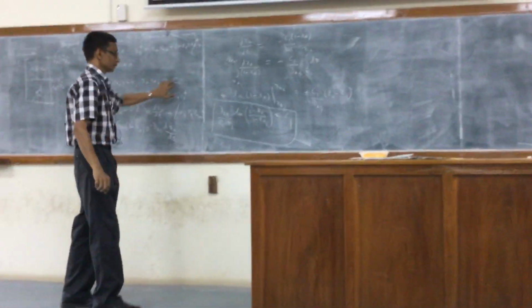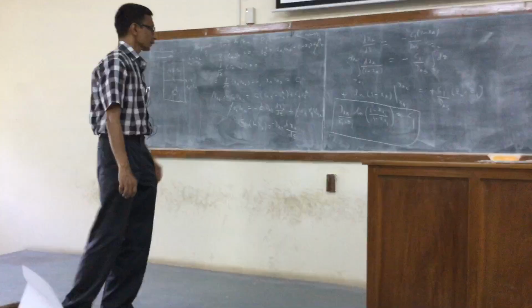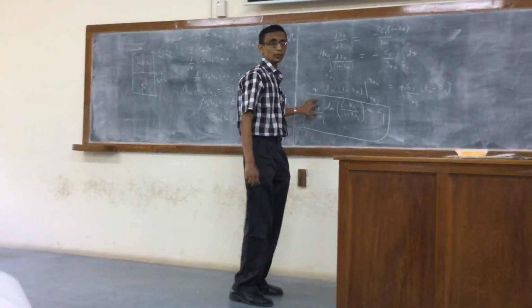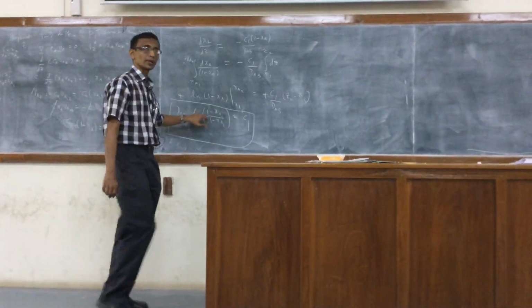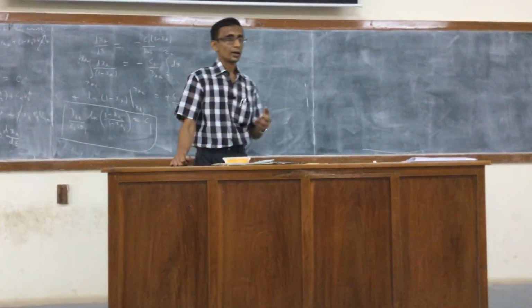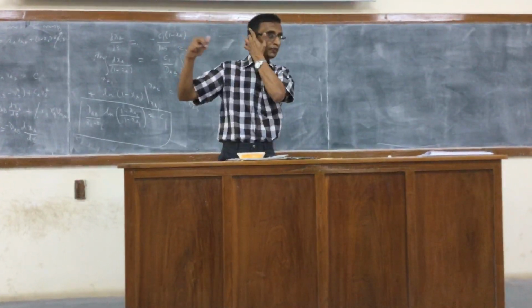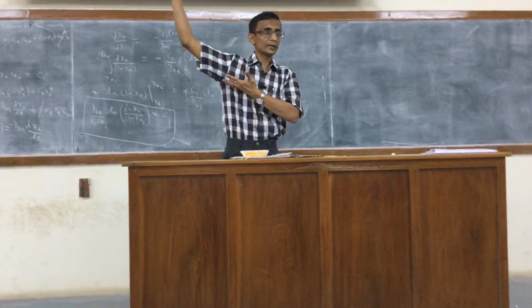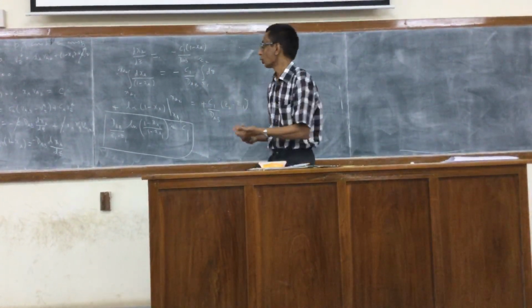We find this constant C1, right? Now can we determine C1? Yes, if I know the diffusivity, if I know the diffusion length, and if I know the value of the mole fraction of A at the 2 points, one on top of the liquid surface and another right at the top of the tube, then I can find C1. Right? So C1 is known.